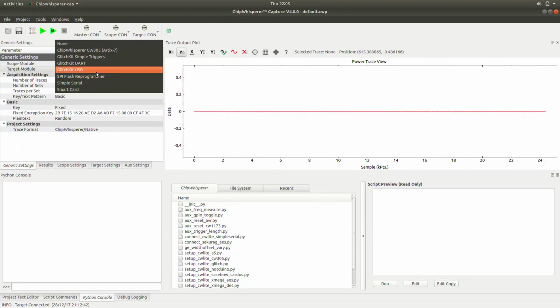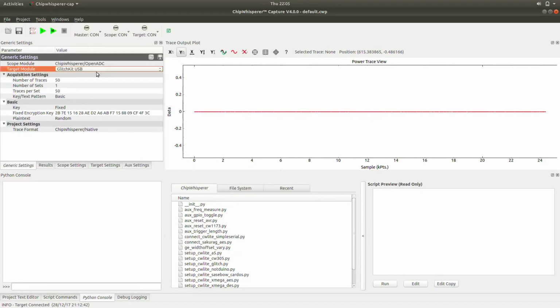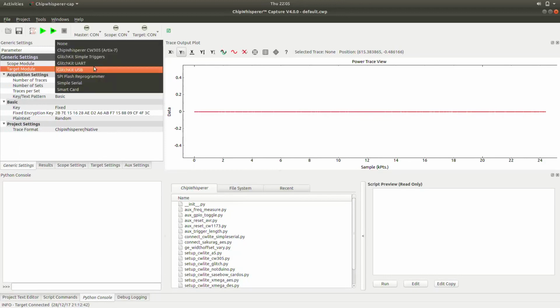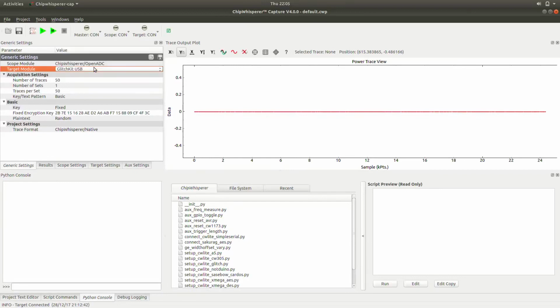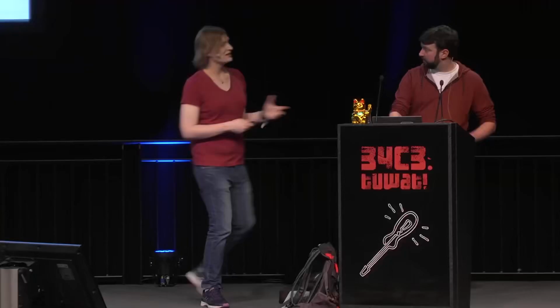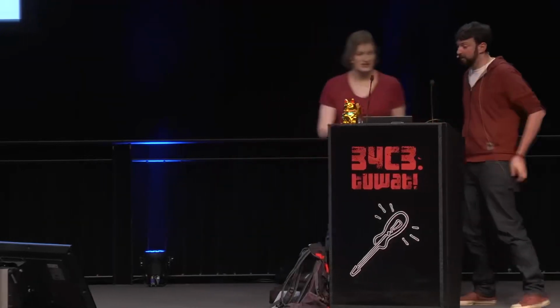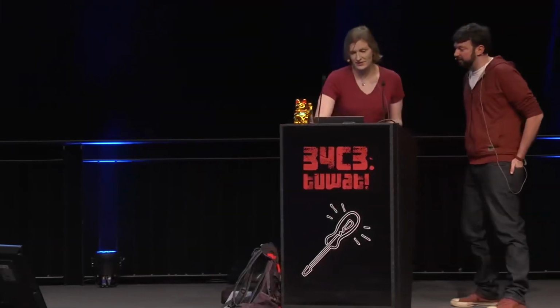Right, and so the process of configuring this: instead of selecting the type of target directly, you say, okay, I would like to talk to the GreatFET that's running a USB stack, so I'll select GlitchKit USB. Then from the UI you can immediately configure, yes, I'd like to read a device descriptor, and I'd like to have that device descriptor be read immediately when certain pins go high. So you can start building everything you need to walk the interface.